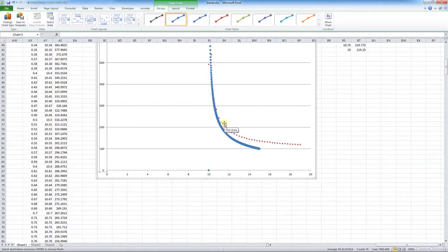The power of the J contour that we're going to take a look at next time is that we'll be able to use an energy measure to relate to the stress intensity factor, either for elastic or elastic-plastic material behavior. But that J contour integral will help us capture that singularity without such a level of refinement. Still have to have a very nice, well-refined crack front, but we'll explore some options again with ABAQUS and with a piece of software called FEA Crack.